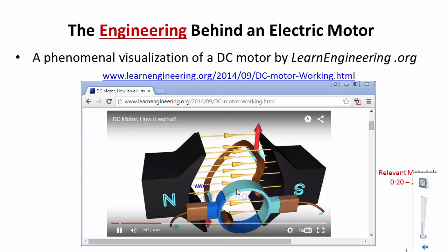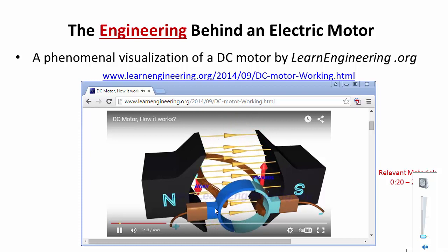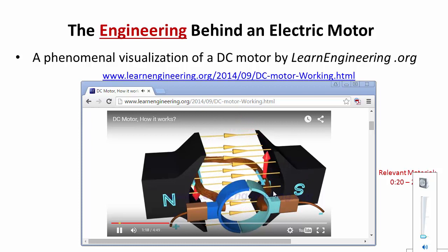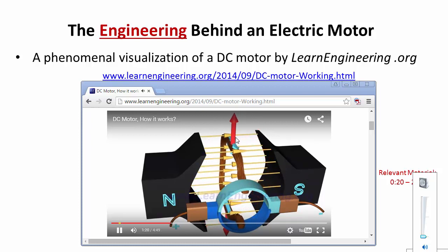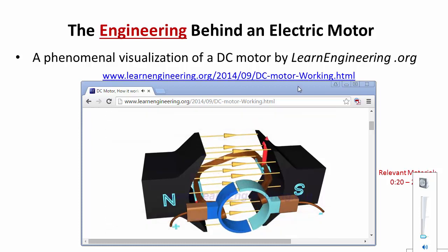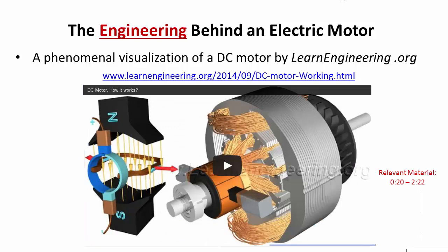So as the thing goes around, you notice that by design and due to these slits, you can use the commutator rings to actually switch the direction of current, and you're doing that to switch the direction of force. So notice that the armature comes up here, and the momentum carries it down into this region, and they're just continually switching back and forth.